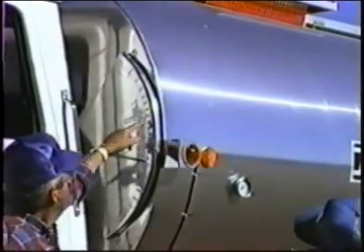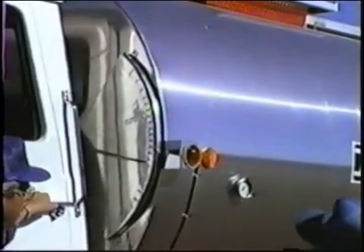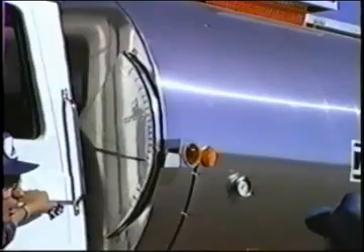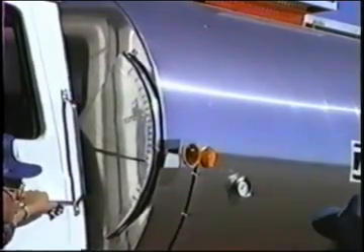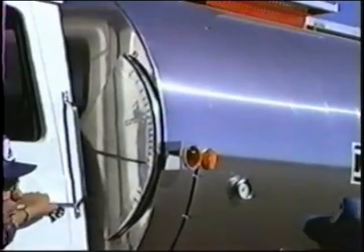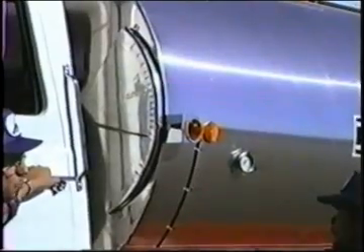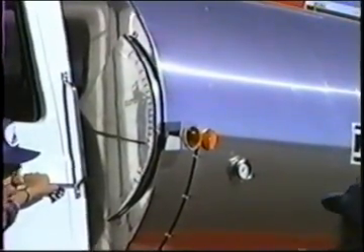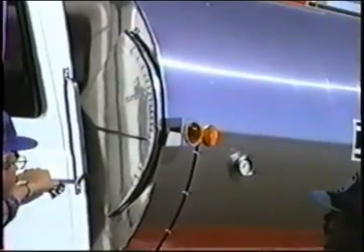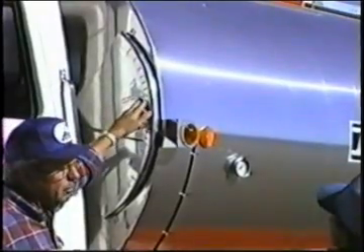This has a note on it: do not fire burner below 700 gallons. The reason for that is we have to have liquid covering the burner tube in order to fire it. Liquid must cover the tube in order to take heat away from it. If we were to fire the tube without liquid covering it, say it just half covered it, well then the top half of the tube would become red hot shortly. When it becomes red hot, it'll ignite the vapors that are in the tank, and that ruins the whole rest of the day. So be certain anytime you're heating that you're above that fire line.